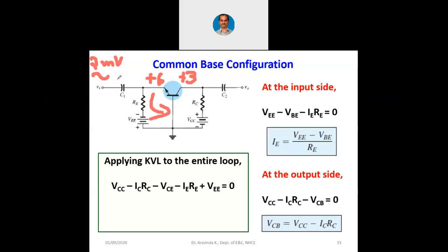Okay. So that way, input, even if you think that how emitter can have input, emitter is having an input of AC itself. Now, even if we replace emitter with collector, collector with emitter, the circuit will work in the same fashion. Why? AC signal can move in both directions. As far as AC signal is concerned, there is no collector, there is no emitter. Only for the DC biasing, there is collector, there is emitter. So always amplifiers and oscillators are basically DC circuits which are handling AC signals. Remember this.